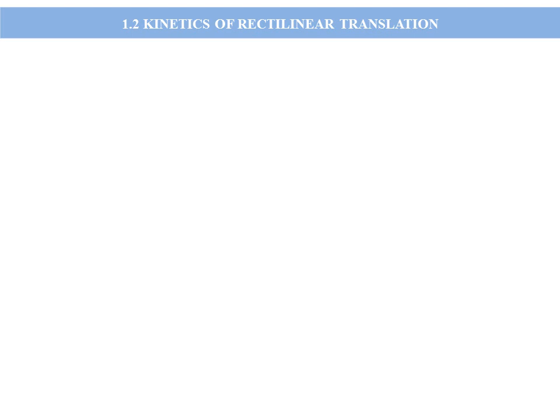Okay. Now, coming to our subject, kinetics of rectilinear translation. First, we have to study the equations of motion, which are Newton's second law of motion. The main equation of motion is Newton's second law of motion. We already know Newton's second law of motion, F is equal to ma. Now remember that F and a are vectors. So you should remember it like this: the vector F is equal to mass into vector a.